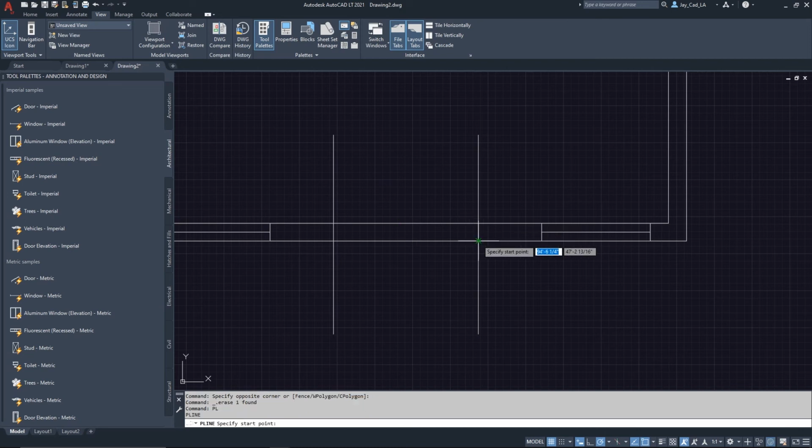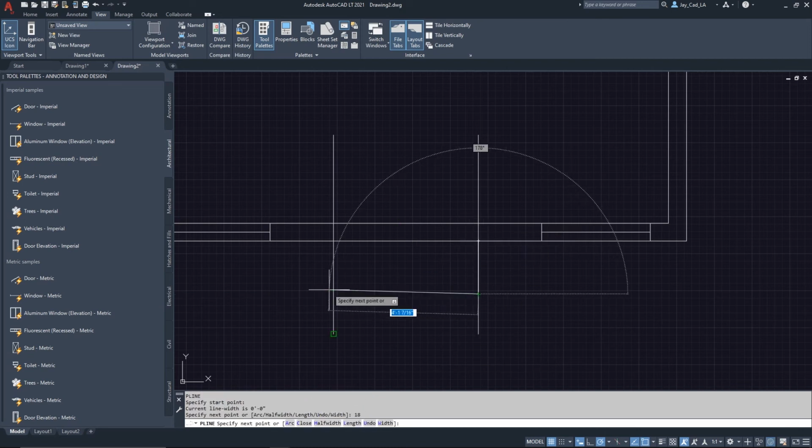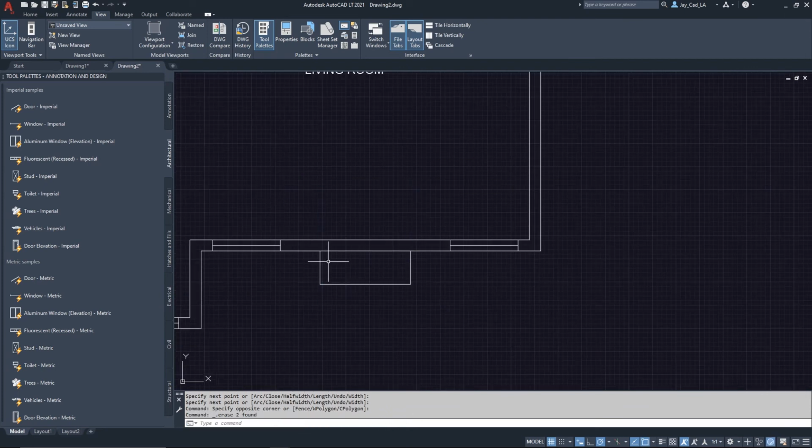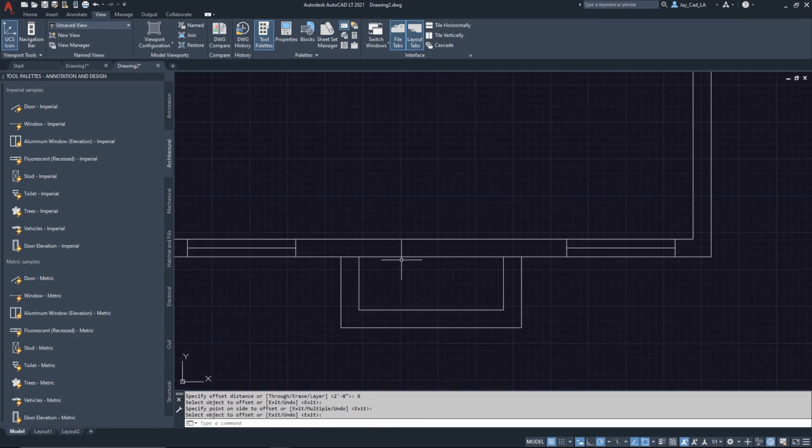And then I'll do a polyline from this corner here. Let's say we go outside for the fireplace by 18 inches. And then I'll do here to this point, and I'll get rid of the references. And I'll offset now by 6 inches like this. And then I'll extend these guys to here, and then I'll trim this portion here and here. And then let's just add a line over here. Okay, and then let's join all of these lines together.